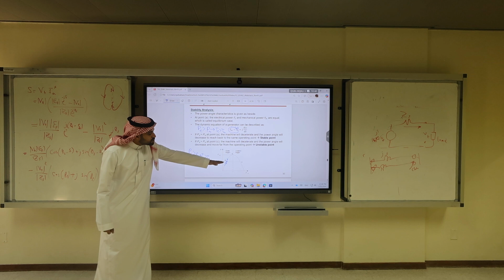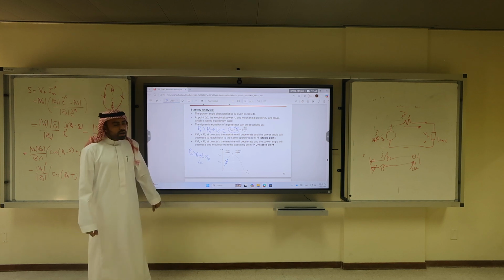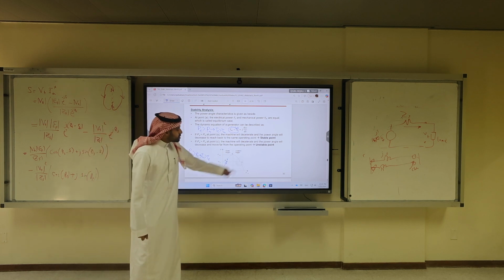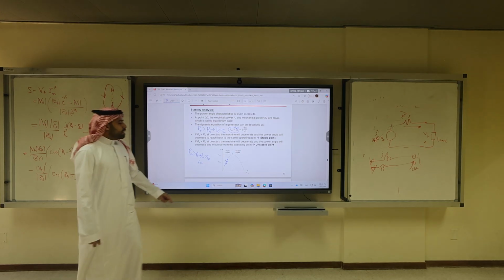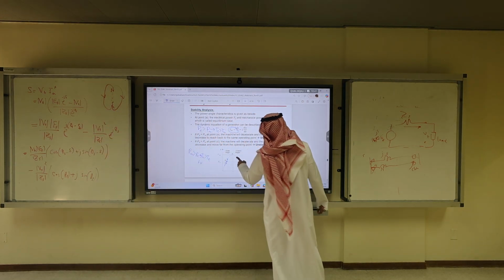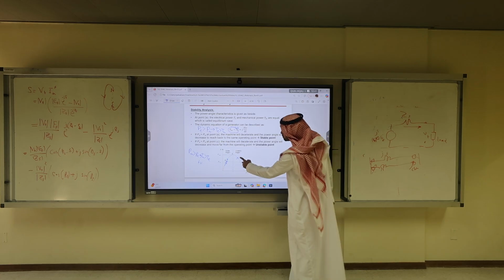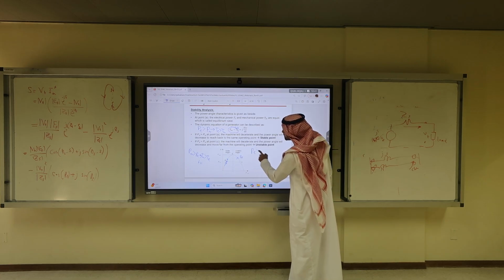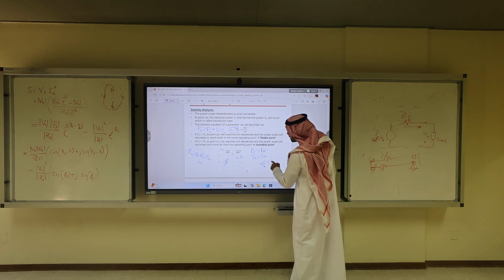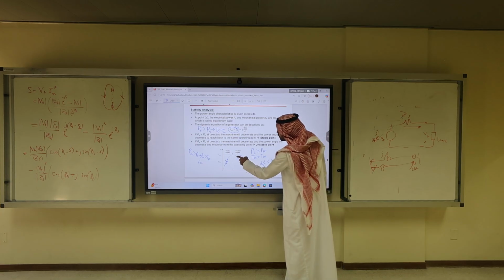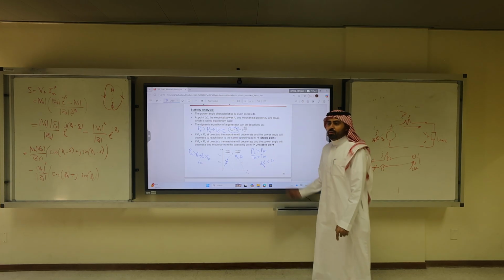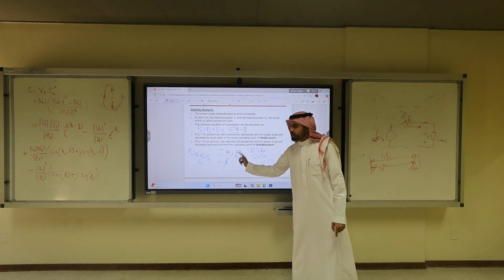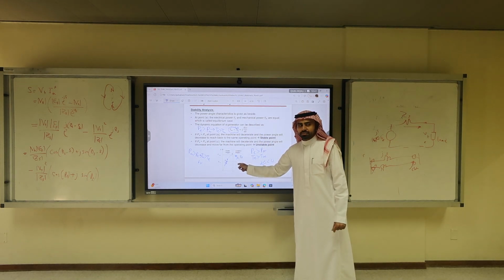So this is the definition of stability. If you go to the unstable region, let's say the electrical power is here. So P electrical is larger than P mechanical, so torque electrical is larger than torque mechanical, so d omega dt is less than 0. It means I'm going this way, to the 90 degree. So this is unstable. You see it?